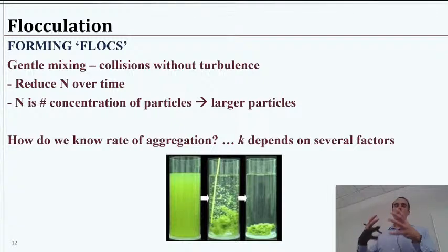So when we're thinking about whether we destabilized it properly, the ionic strength goes into that. Now we understand kind of how and why that works. We might add some other stuff, some polymers that could bridge over and grab the particles and stick them together. Whatever we do, now we have to give them time to mix. And so this is the flocculation.